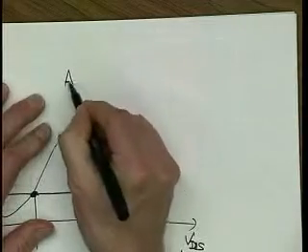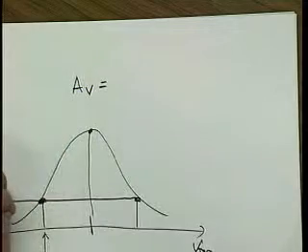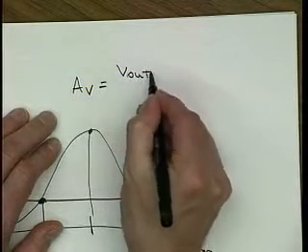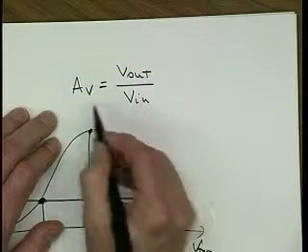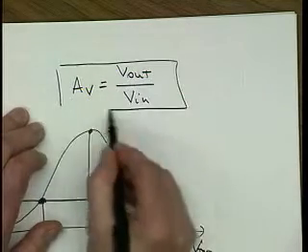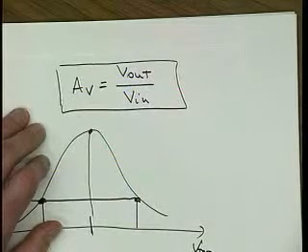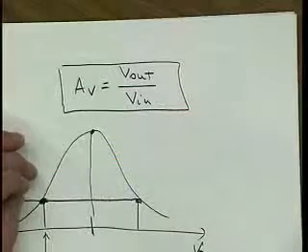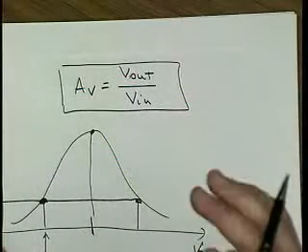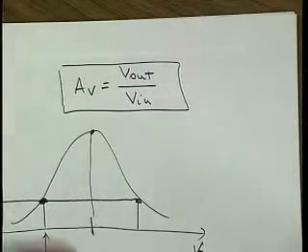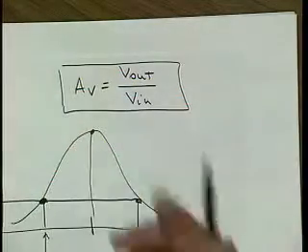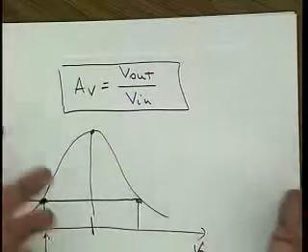Well, you know, for the gain AV, there are really two possible definitions. One of them, the simpler one, is Vout over Vin. And actually, that's the one that usually matters for an amplifier, right? And then there is also the small signal gain, where we say, if we have an amplifier that doesn't even work for Vin equals 0, like the amplifier that we just designed, right? We have to have at least a threshold voltage on the gate or something like it. Then we have this small signal gain.